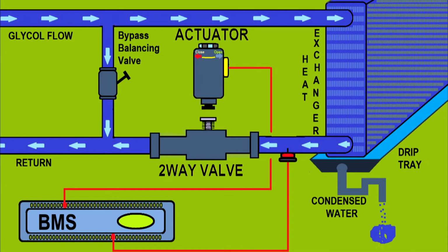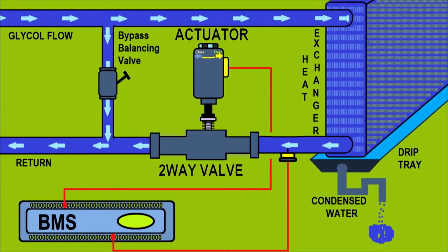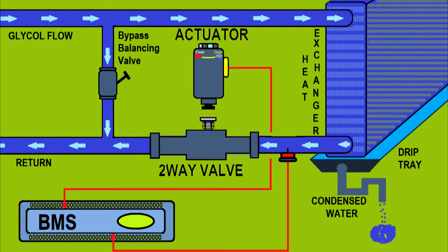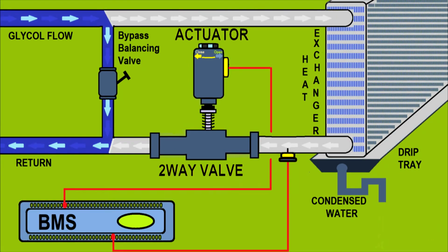This is a very interesting thing. Sometimes the valves, look at the actuator, the valves are freezing. That little shaft is blocking and the valve remains open. So your office will freeze even if your controller tells you that the heating has been turned off. There's nothing you can do about it. And until you repair that little shaft to stay in position and to close the valve, you cannot divert the entire quantity of cooling agent. So the cooling agent will constantly pass through the heat exchanger, and then you probably have to stop the fan. But if you move air through a very cold heat exchanger, you will always have a cooling process in progress.